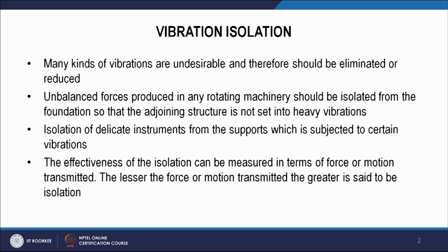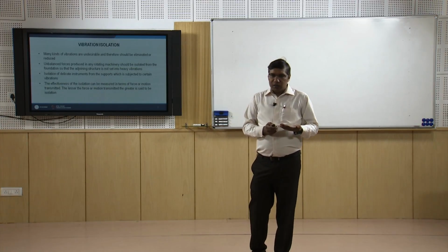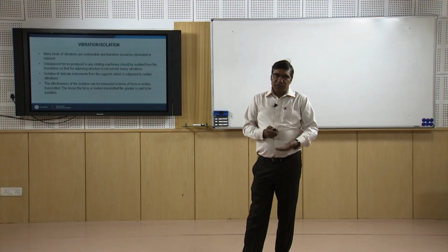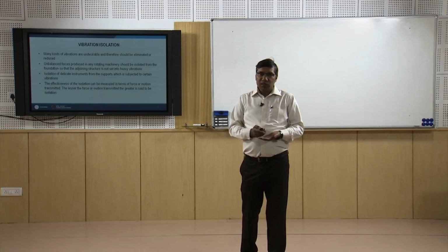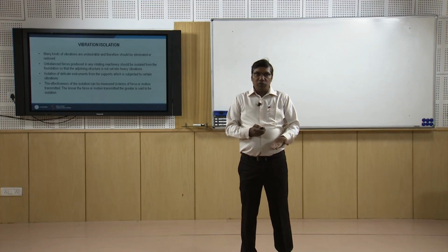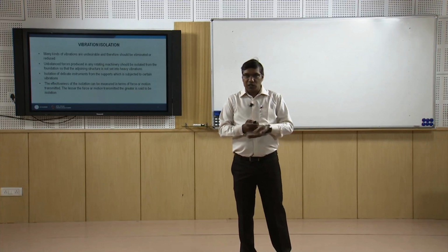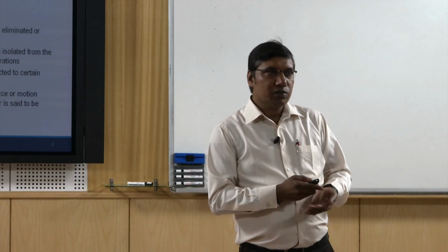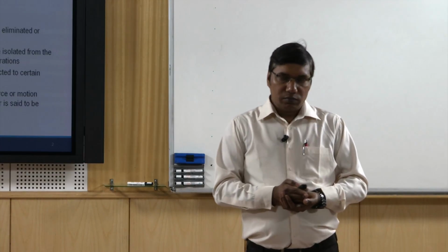So how do we measure the effectiveness of a vibration isolation? We measure that if, after introducing the vibration isolation, the force transmitted to the foundation, or the motion transmitted from the support to the instrument or some sensitive article, is reduced, then we say that this is an effective vibration isolation.